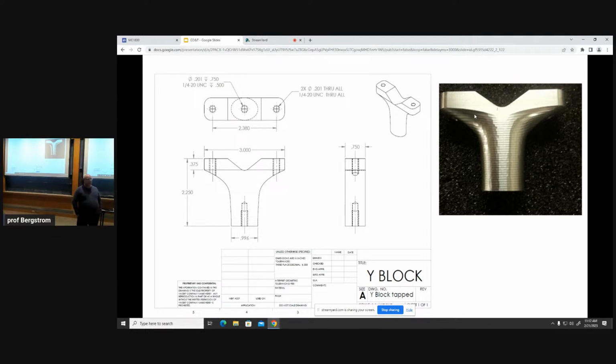Exactly. So you could, as long as your radius is not too big or too small. If you get too small, you get it lost in the bottom. And ours has, I think, a 1/4 inch radius at the bottom. But yeah, with a V block, you can hold a bunch of different diameters, and it'll locate it either sideways in the vise or straight up and down in the vise, depending on how you orient the V block.